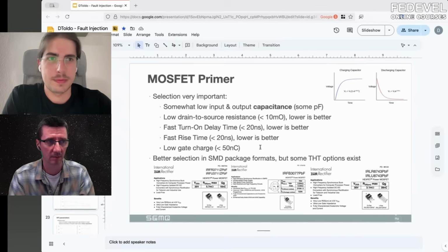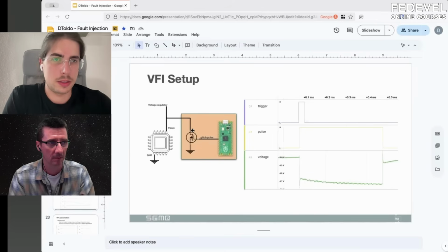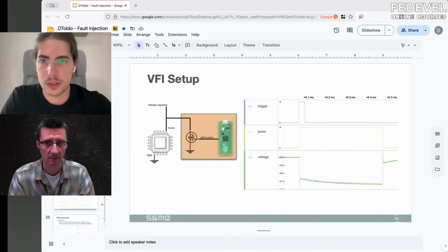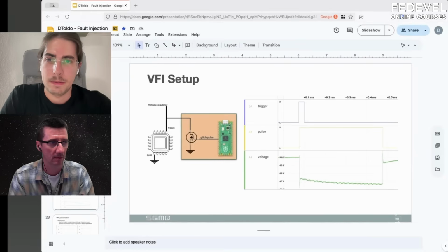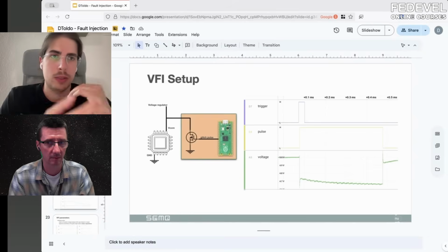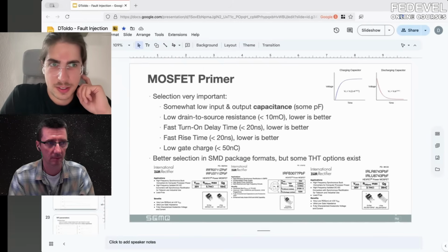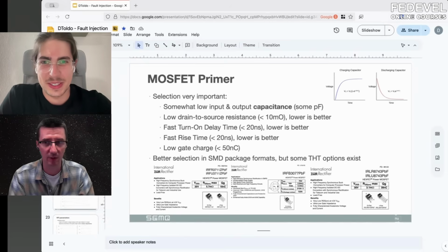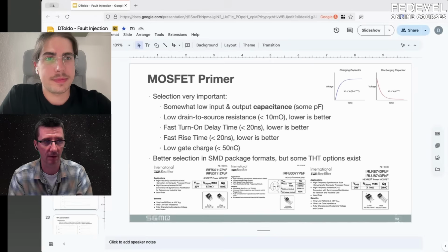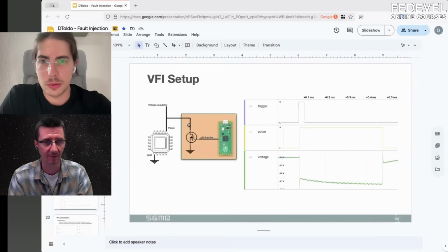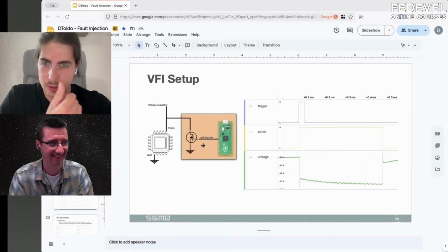So yeah, there's some work for voltage fault detectors as well. I mean, this is a crowbar glitch, because we use a crowbar to connect voltage with ground. But the more you get into these attacks, you can always do more sophisticated things. We usually do as much as necessary. Sometimes it just works like this, and then it's fine, because the circuit that we have now is very simple. I really have essentially 100% this signal, nothing more, nothing less. This circuit, yeah.